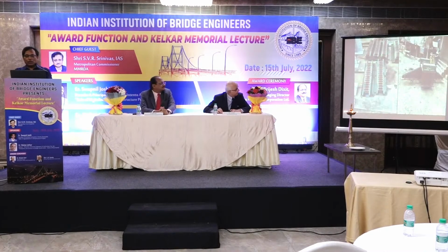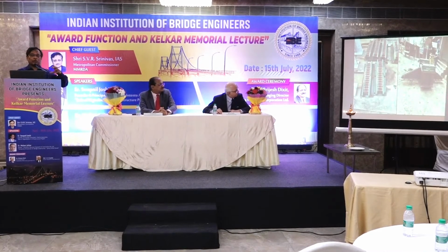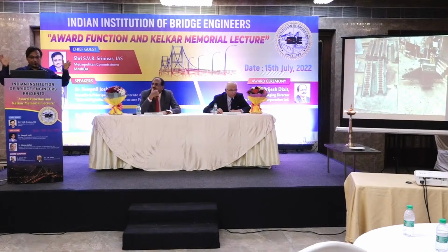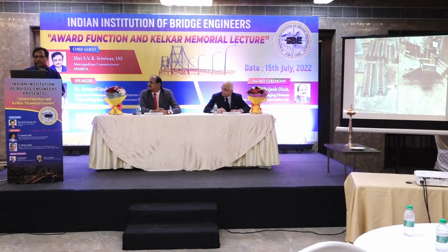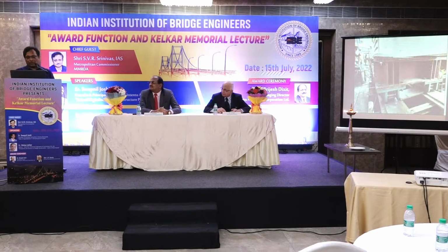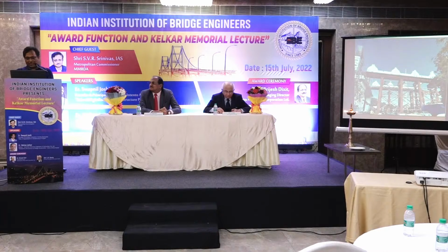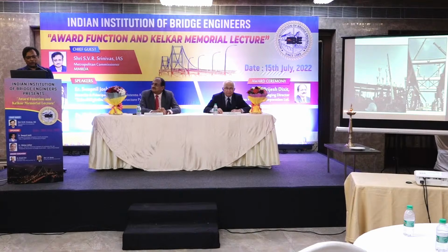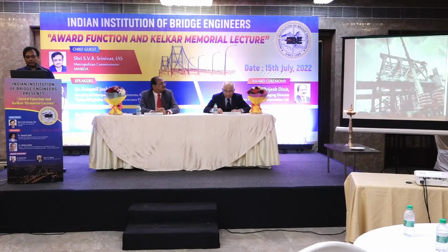We are taking the blocks, and we have used the Hillman roller. I think this is a Hillman roller. They have used it, but it is used sparingly. But 600 ton load supported on 4 trolleys was another challenge. How to support the entire structure, and trains are passing below the bridge. So the Hillman roller was used there. Again, these are supported on the temporary structure. If you see the size of the column, it was almost 14 to 15 meter high. A lot of cranes were used, a lot of constraints, but the main part is I want to show you this entire 80-meter girder.